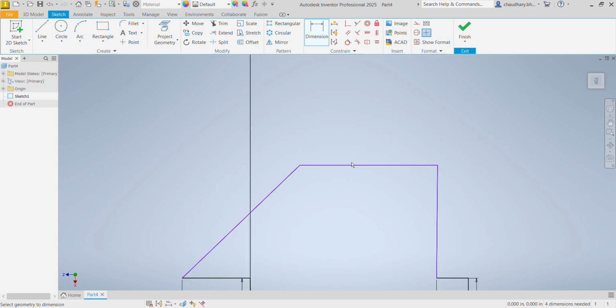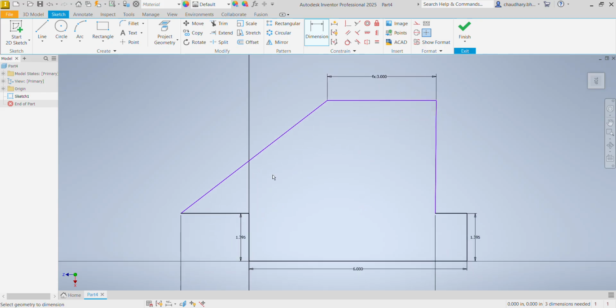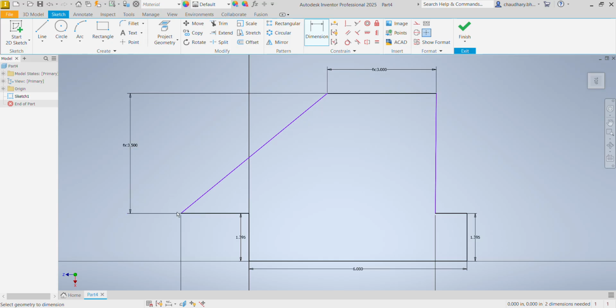The tip chord is the length of this horizontal line up top. So we type in tip chord. The height is the distance between the tip chord and the fin tab, so this line and this line. That's your height. And the sweep is the distance between this front point and the front of your tip chord, and it's the horizontal distance. So this is your sweep.